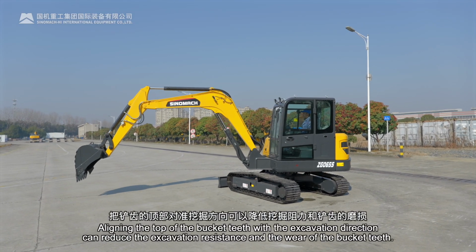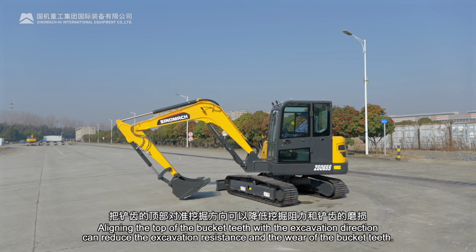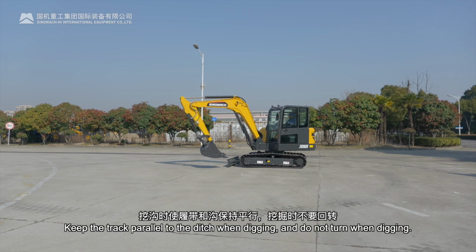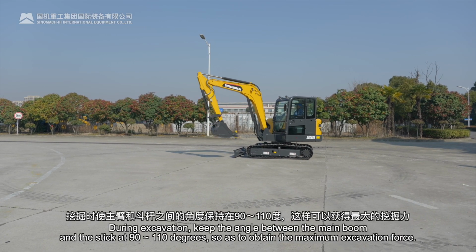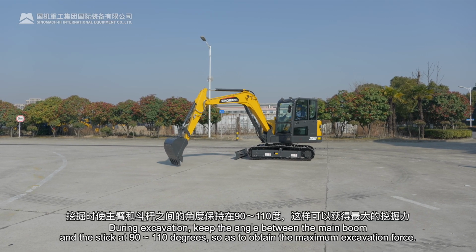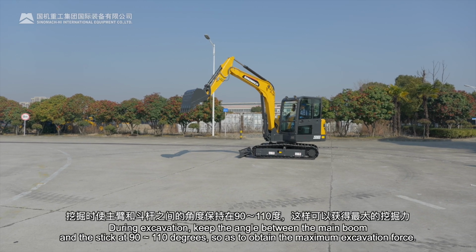Aligning the top of the bucket teeth with the excavation direction can reduce the excavation resistance and the wear of the bucket teeth. Keep the track parallel to the ditch when digging, and do not turn when digging. During excavation, keep the angle between the main boom and the stick at 90 to 110 degrees so as to obtain the maximum excavation force.